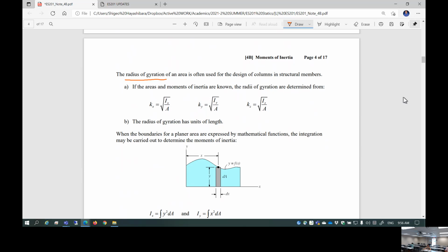So how much radius is it? That is going to basically characterize how easy it is to spin your spacecraft in a certain direction because the distribution of mass is given by the mass moment of inertia. So that's the radius of gyration. The terminology originated from spacecraft design, so it's kind of difficult to visualize in structural analysis. But radius of gyration is a similar concept.